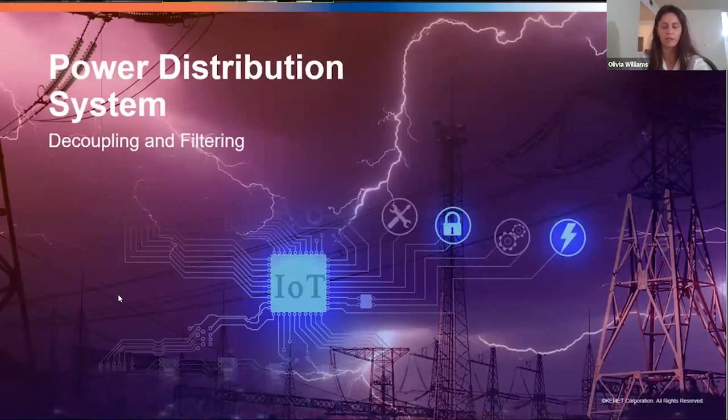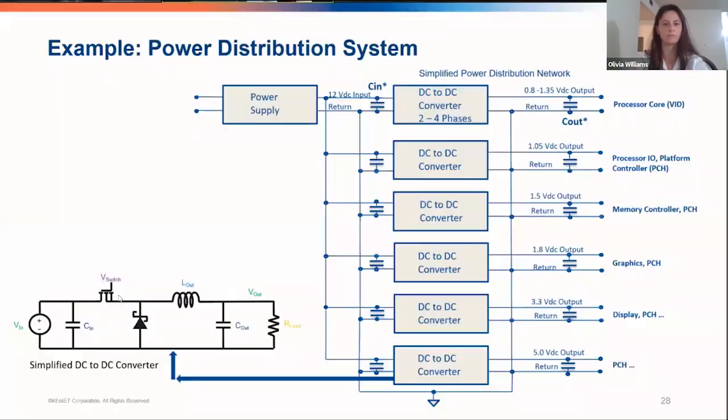And then let's look at an overall view showing where we use both the decoupling caps and the filter caps. So it's kind of worth pointing out that in today's systems, we have multiple converters attached to the same main power supply. And this can create design concerns in terms of having enough power reservoir available at both the input and the output of each section. And as a result, we need to take care to place the capacitors near to the converter input and output so as to minimize their parasitic effects and the impact it has on the system so that it doesn't corrupt it too